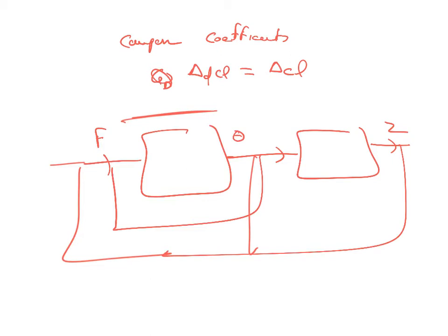Okay? So you start with the open loop transfer function. First compute the open loop transfer function. Simple. Take a Laplace transform, find the ratio of input versus output. And then see what you want to do. You want to track a reference output. Then the next transfer function is between Y and Y reference.